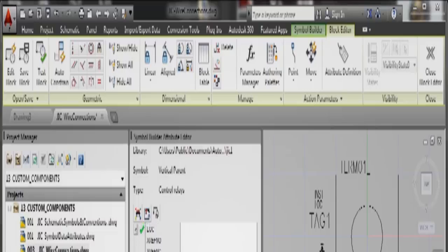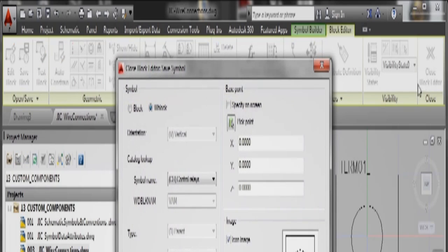So I've now added everything that I need for this particular block. I go close block editor, make sure it's a block in the drawing itself. Just do the base point again. You don't need to, but just sanity check again, just make sure you've done it. Unique identifier, I'm going to change that 002 there to ACADE, AutoCAD Electrical. Press tab, and you can see that's easy to spot now in the drawing.